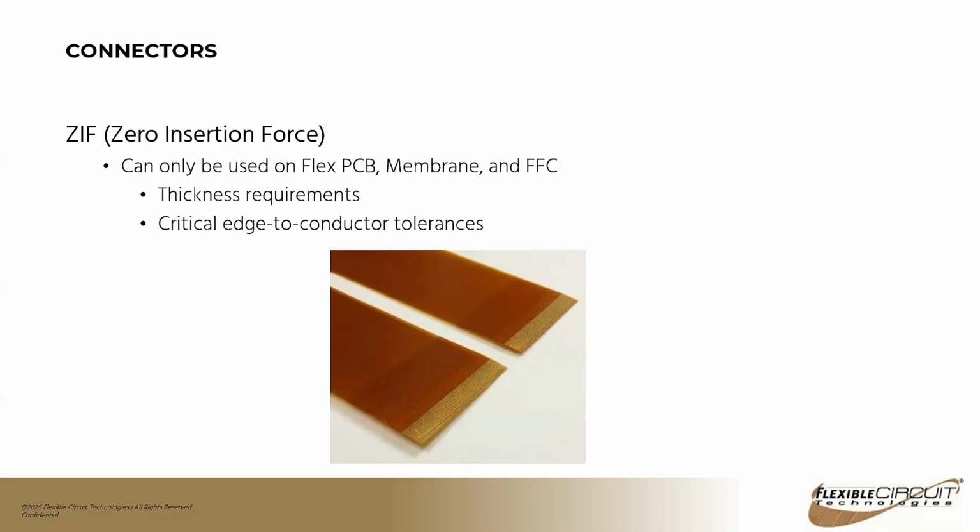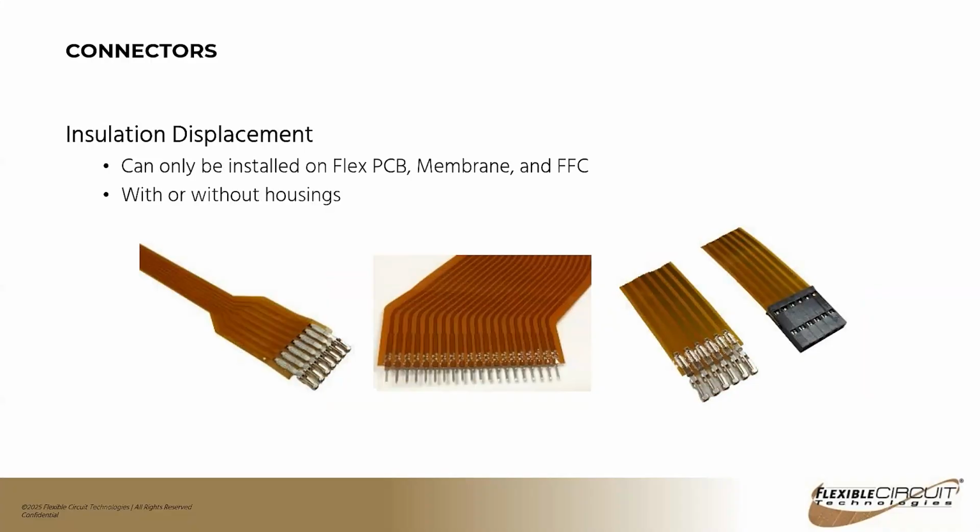So we add polyimide stiffeners as required, and then typically the ends would be laser trimmed or hard tool punch and die to achieve that tight conductor to edge tolerance.